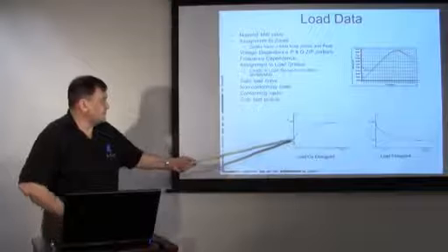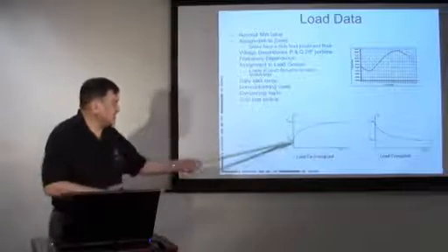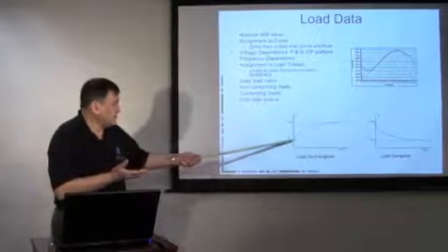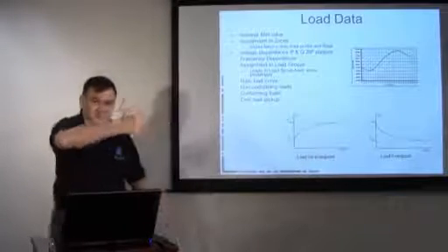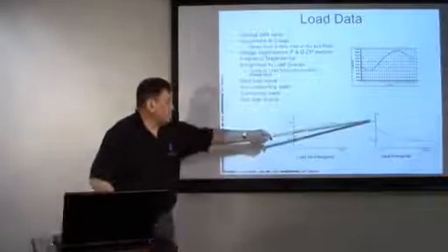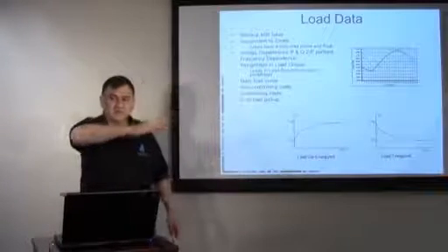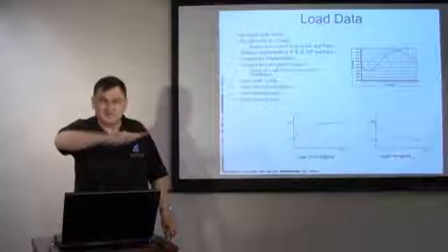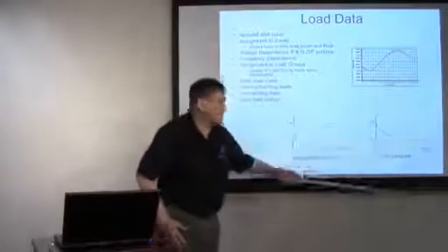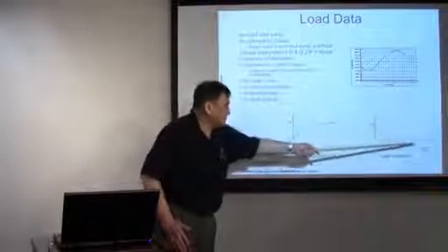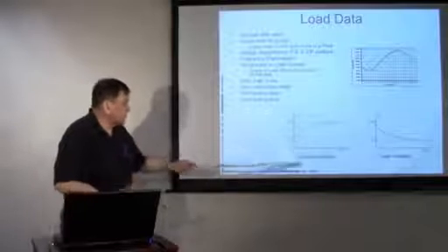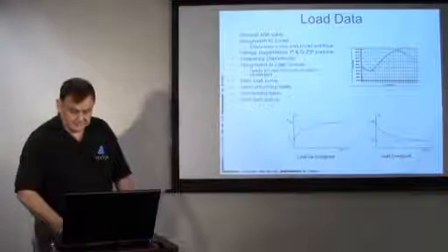And so what's happening is the amount of cold load has actually increased. While the feed is de-energized, we have this hypothetical value called the cold load, which is the amount of load that will come on right at that instant. And then once that load does come on, over time, the air conditioners will bring the temperature in those homes back to the actual desired value, and so you'll get your diversity back again. And so after a certain period of time, you get back to the normal value. And so for restoration drills, modeling that cold load effect is very important.